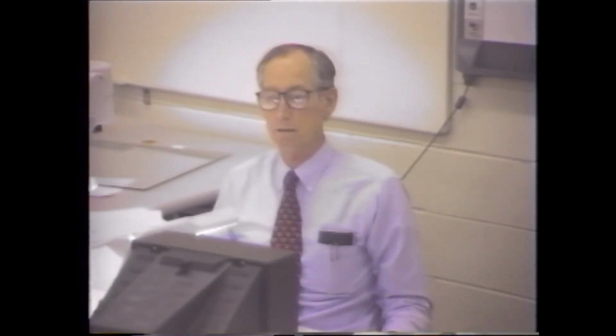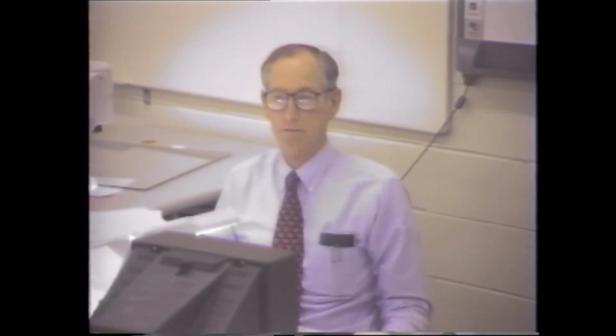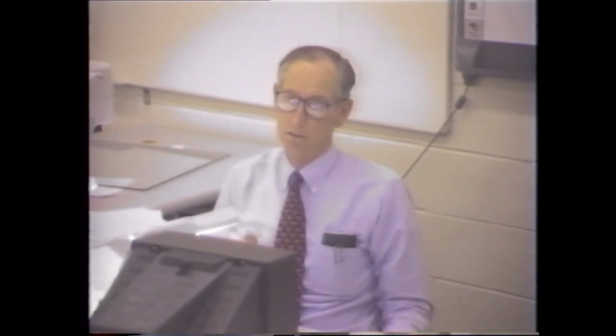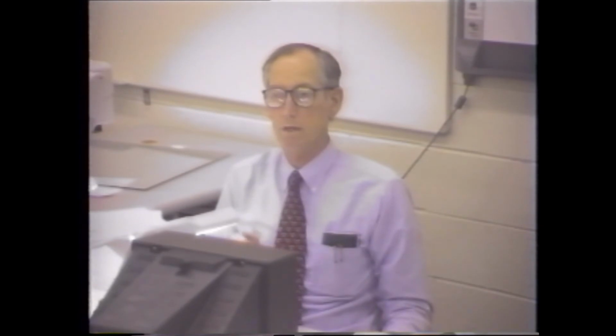However, they might give you a really tricky wording and say you have so many standard cubic feet per minute, but it's entering at 200 degrees F. If they do that, the key is the standard cubic feet per minute. That is a certain temperature. It always refers back to standard temperature. So you know the mass by using the density of air at standard temperature.